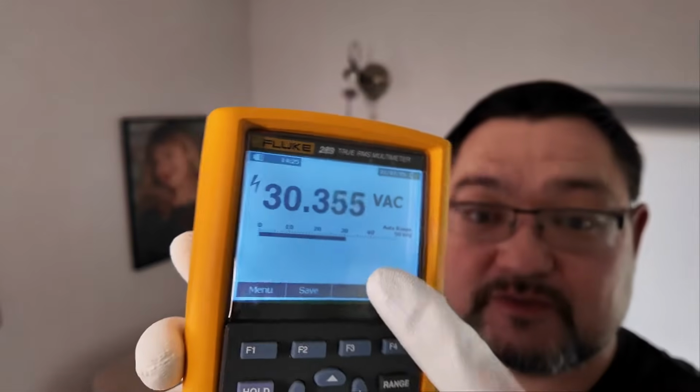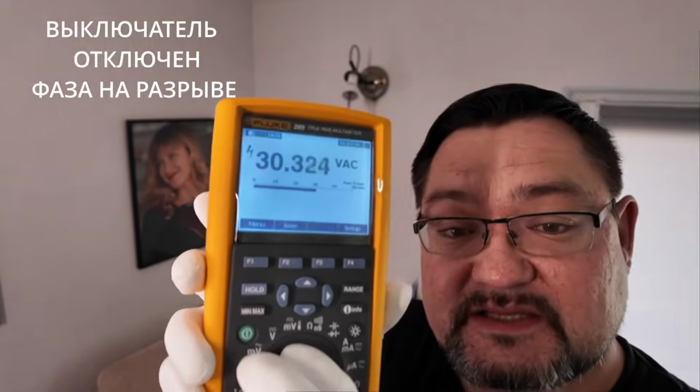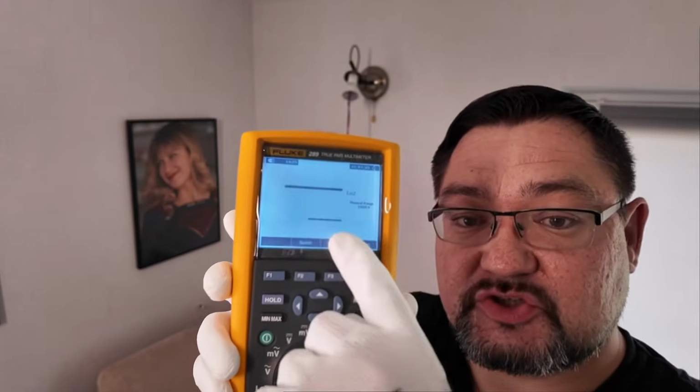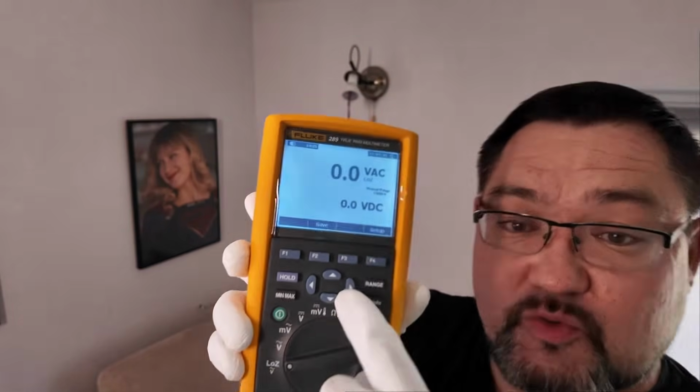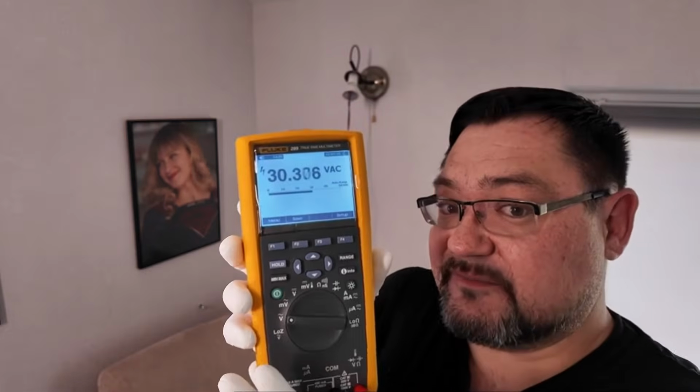And now I'll show you. Here they are, 30 volts of phantom voltage. Yes, this device can deal with phantoms. If we switch to the low input impedance socket mode when measuring voltage, it will show 0. But this voltage is often measured by those who don't have such an expensive device, and people get scared.